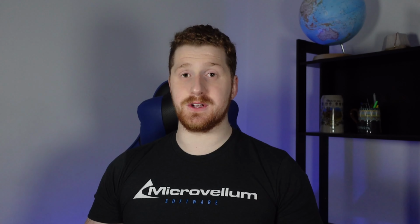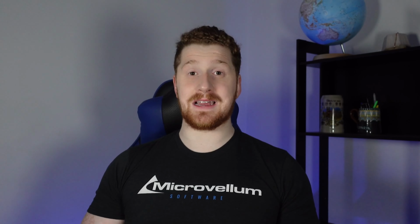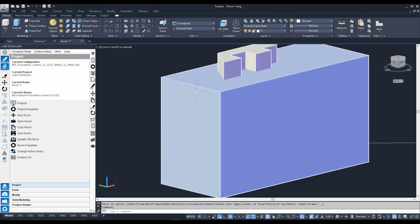Now if I switch this back to my conceptual view, I can see my 3D object inside of this guy. Now I need to make that hole in my cube, and in order to make that hole, I need two 3D solids. One solid that I would like to keep, and one that I would like to pretty much make a hole or cut out from.